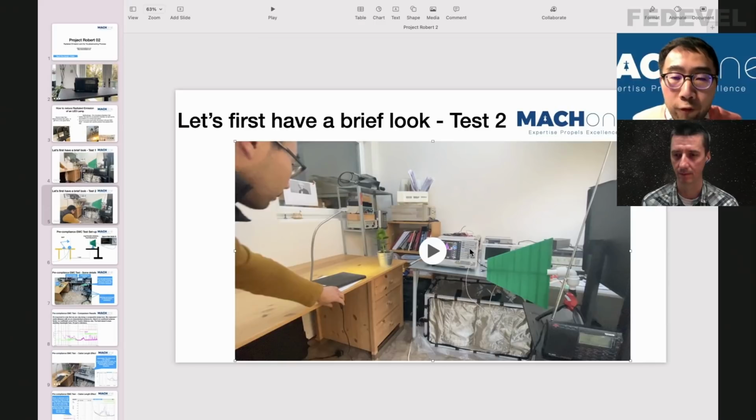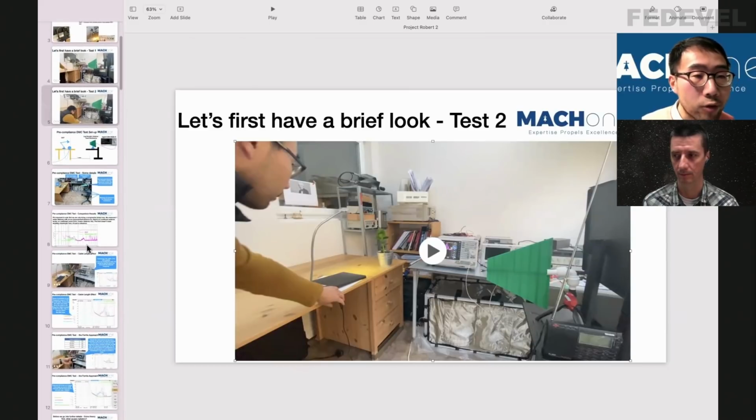So before we do a full-scale operation on this product, often you send a product, let's say this lamp is our design, to an EMC test lab, and they test it and say, oh, no, it's not good. The EMC lab test engineers would always give you some advice. This advice is probably not from the design perspective, but it's quite practical. In this case, they will probably tell you, let's put some ferrite on the cable, or let's shorten the cable. Let's have a look at what this means.